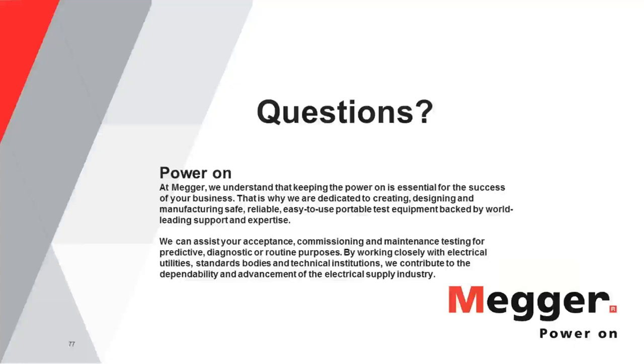Connected but not energized. Okay, so the thing to consider here is that whatever is connected to the other end will also be tested when you are testing the insulation. So if you are interested only in the cable part, you should disconnect the other end. And if you don't care about the particular result for the cable, but you just want to see if the entire circuit has good insulation, you can leave it connected, of course taking care of de-energizing the other end and not running a test in an unsafe place.